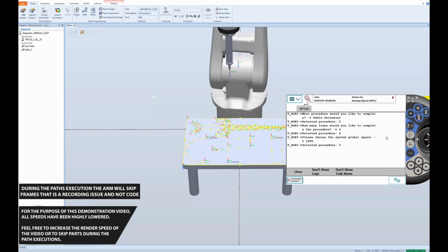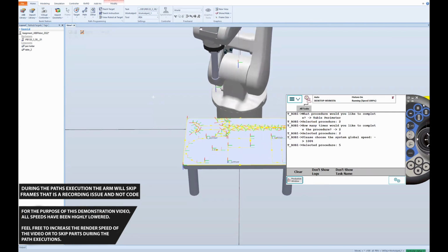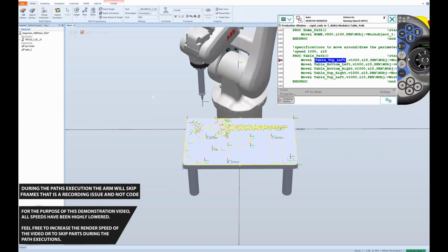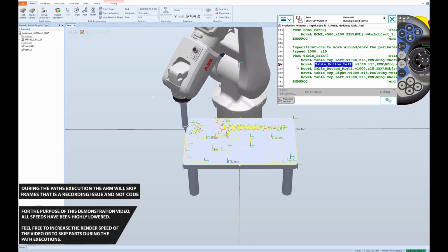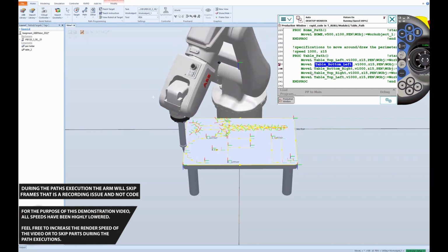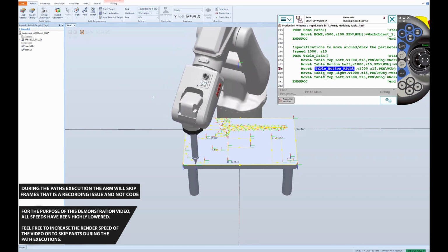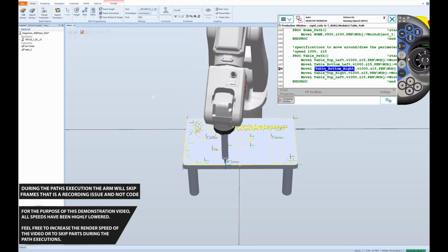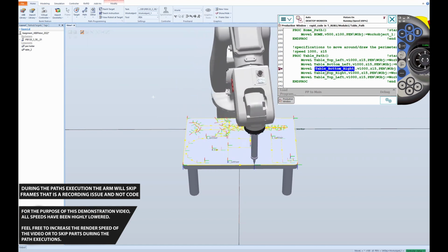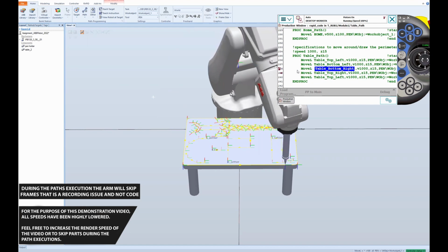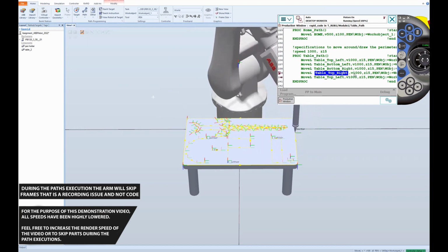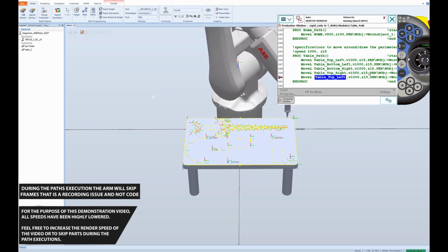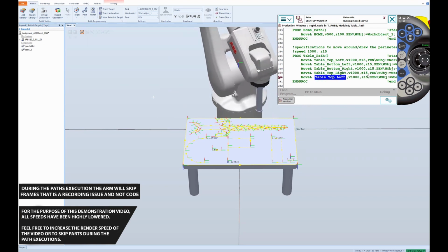Now, once all of this has been done, the robot arm will start moving, as can be seen here. While the robot is running, we can also see the exact procedure that it does in the subroutine representing the path. In this case, I'm using move L for all the different movements with speed V1000 and accuracy for curves of Z15.